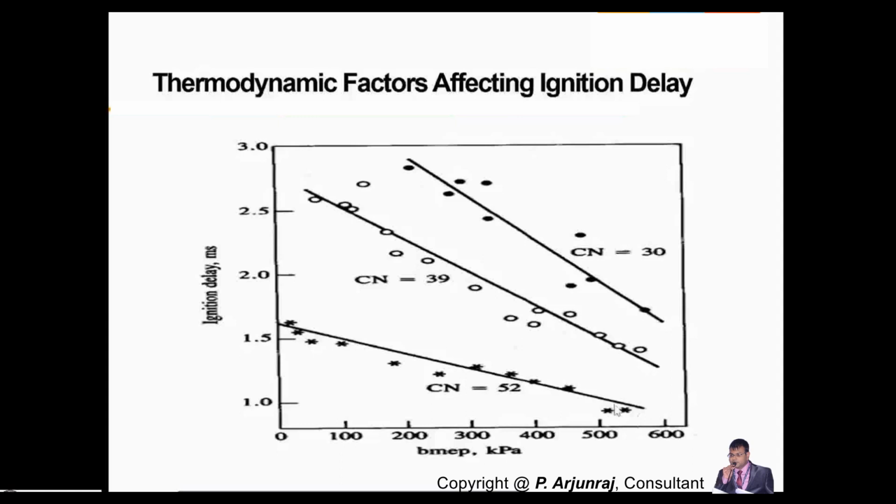But the gasoline engine can be operated at higher RPM also. It can go to higher RPM than that of a diesel. But the brake mean pressure is not that much higher as that of a diesel, brake power is not that much higher than the diesel, and the efficiency is also not higher than that of a diesel. So this is a quite interesting phenomenon between diesel and gasoline.